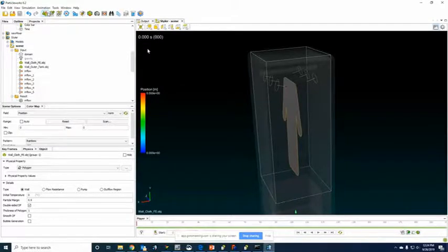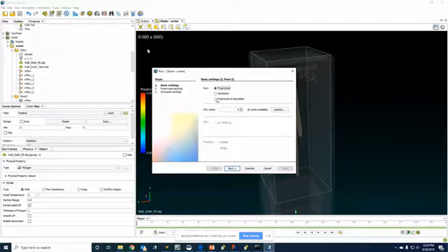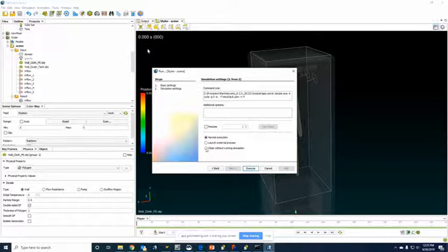And there's one more step there. So you can do this all in one step, but in this tutorial it's broken up into two, where you go into the simulation, and doing this will create some default files that are needed for the co-simulation. So you end up just selecting close without running simulation.